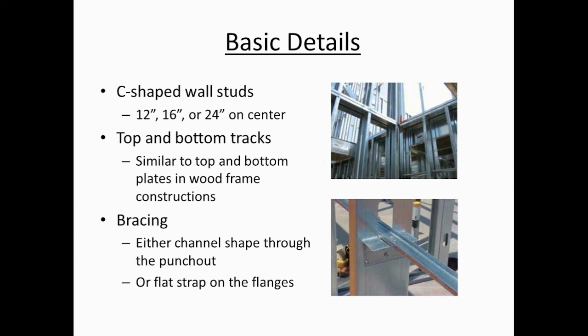So in those applications, we would suggest, recommend, require cold-formed channels going through the punch-outs that are physically attached to clip angles, shown here, that are attached back to the web of the studs. These are spaced vertically at third points, 48 inches on center, whatever the code requires. And if you don't want to do that, you can use, as mentioned here, flat strap on the flanges. I particularly prefer this one. Flat straps on flanges creates problems for the gypsum board down the road, but that's a design issue.